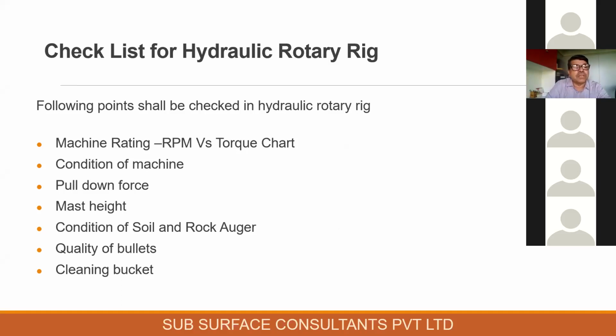Then what is the condition of the machine? Is the machine in decent, good operating condition? Is it serviced properly before coming to our site? If it has done too many piles before coming to our place and it has got fatigued, then this requires reconditioning. So the condition of the machine is very important.